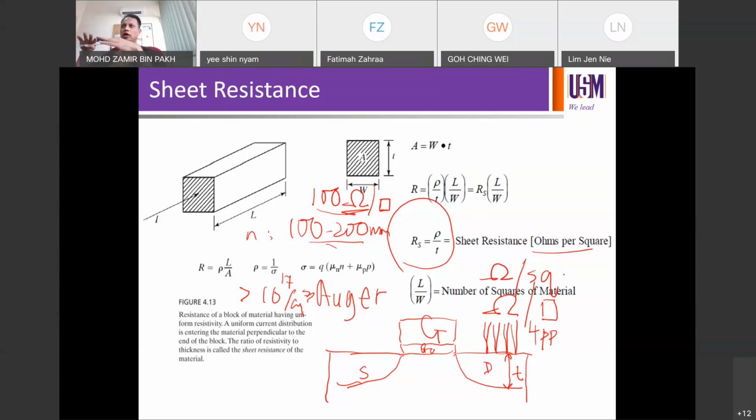You want to go for low sheet resistance, but it cannot be too low for some reasons, right? If you look at the solar industry, the sheet resistance was actually around 80 ohm per square a couple of years ago, like what they are doing now in Jinko Solar, JA, and some other silicon-based solar cells. But this value is increasing over time. They want to go gradually to 100 ohm per square, and then maybe in the next couple of years 110, 120 ohm per square, which is the opposite of what we are trying to achieve. And there's a reason for that.